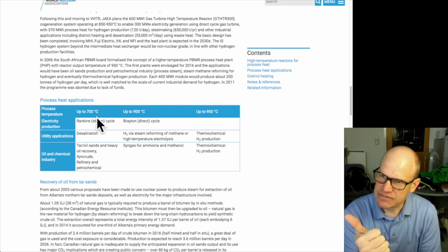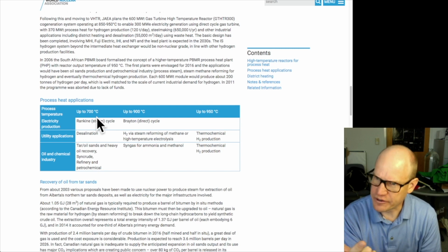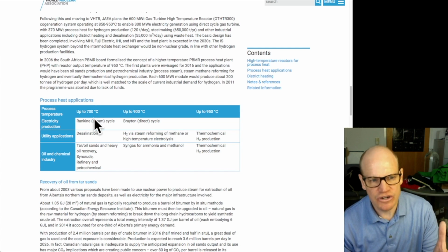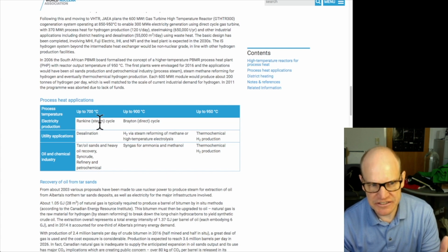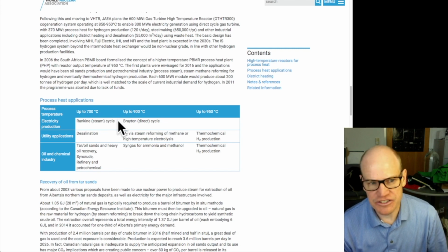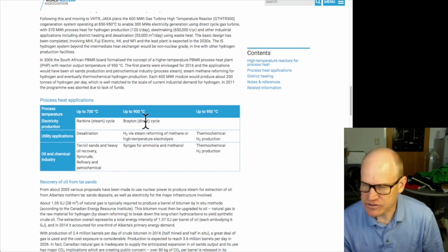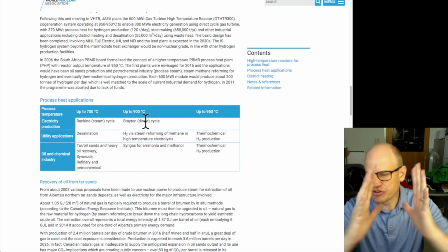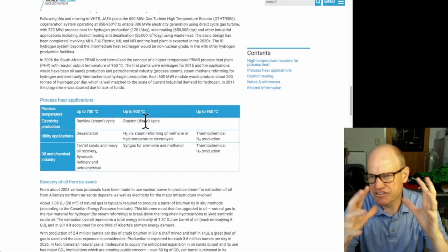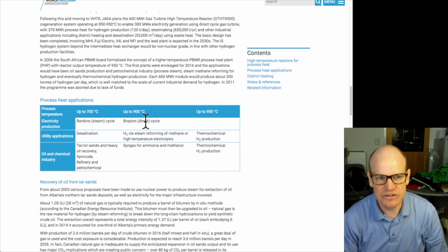Natural gas generators don't use the steam cycle, but coal-fired power plants do. So if you have a coal-fired power plant, you're going to use the Rankine cycle, which is the steam cycle. The natural gas power plants are different. They use the Brayton cycle, which is like the jet engine cycle. With a jet engine, you bring in air, you compress it, you light it on fire, and then the exhaust comes out the other side. So you still have the same steps of bringing in air, compressing it, raising the temperature, and then exhausting the material.